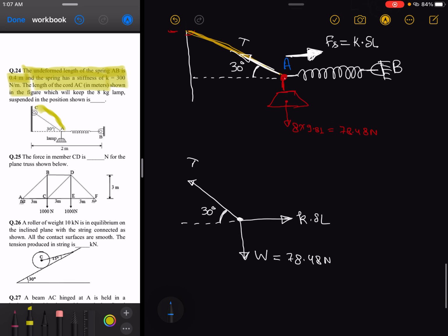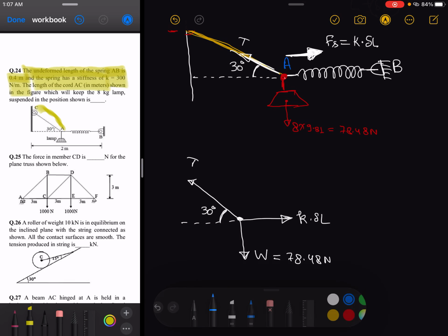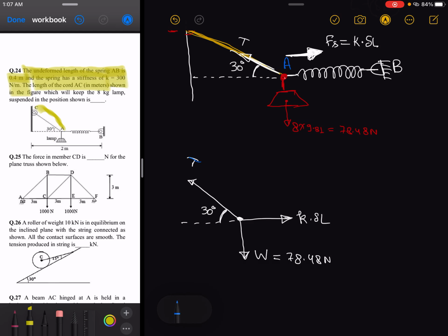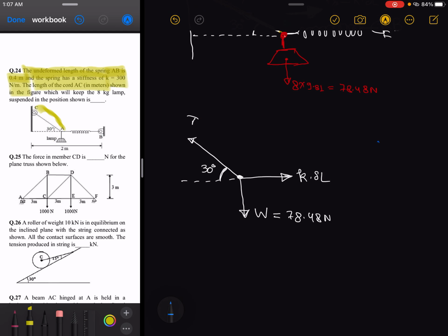So what we are going to do, we are having this 3-force system passing through a point, in the same plane, means coplanar and concurrent force system, then we can apply Lami's theorem very easily. If you know only one force and any one of the angles, then you can find all the forces in the question. So if you observe carefully, this angle is 90°.